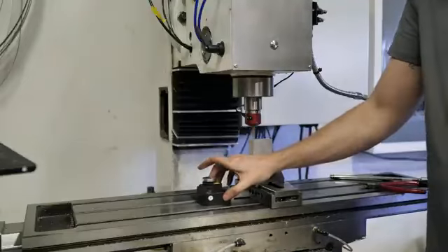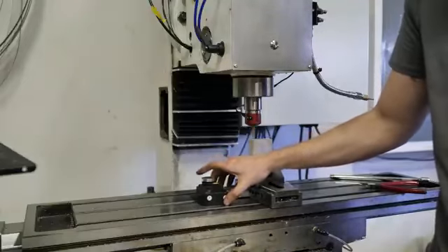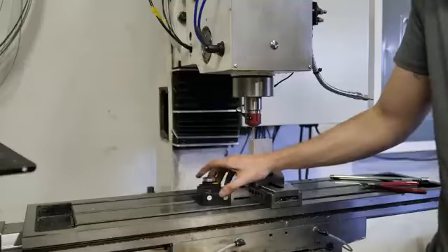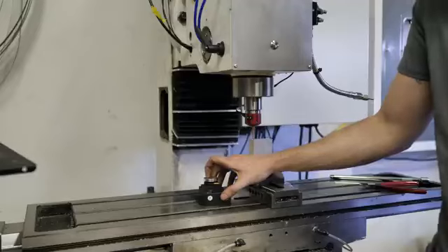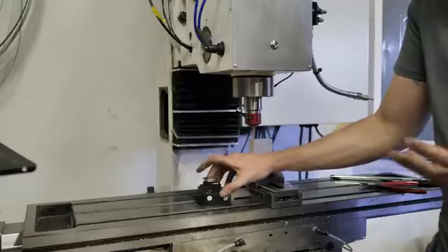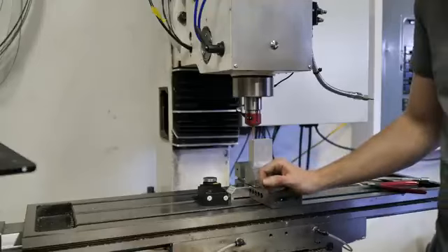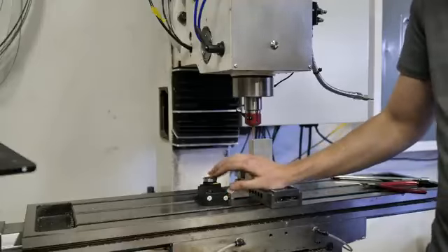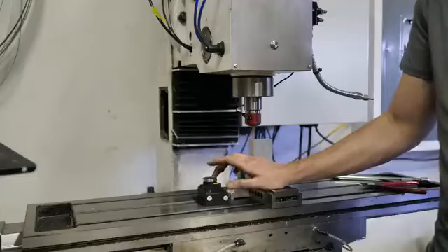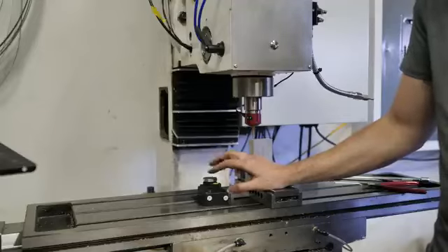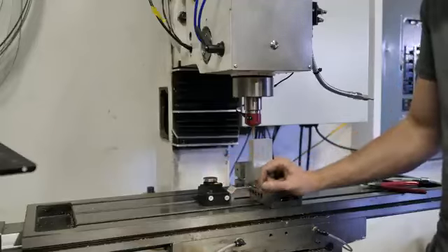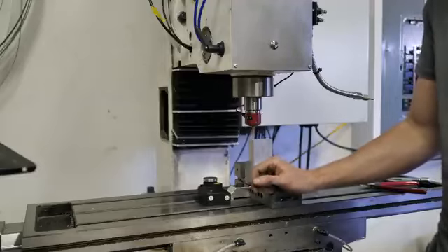One thing about Mach 3 that is frustrating, and something that Mach 4 did better, is Mach 3 only allows you to have one probe at a time. It only allows one pin for the probing function. And you can see I've got 2 different probes here. So every time I do tool height offsets, I have to go into the settings and change what the probe pin is being used for, which is a little frustrating. Mach 4 would let you have, I think, up to 4 probes at a time. So if anybody's still doing development on Mach 3, maybe add that.